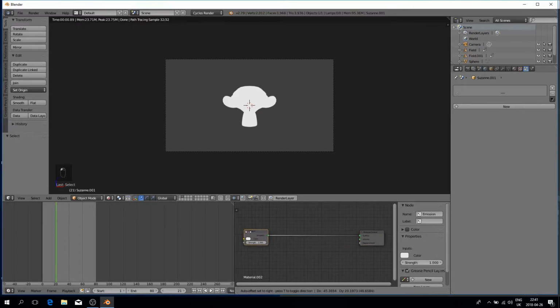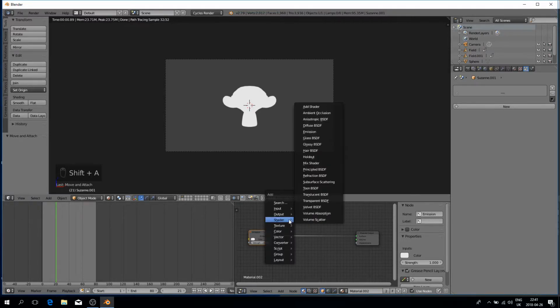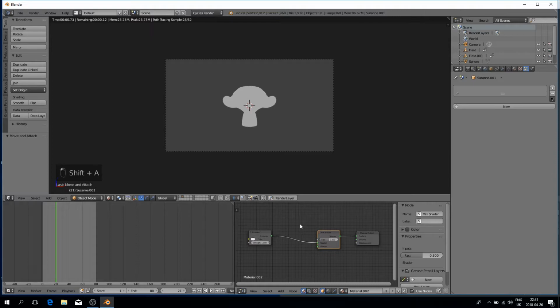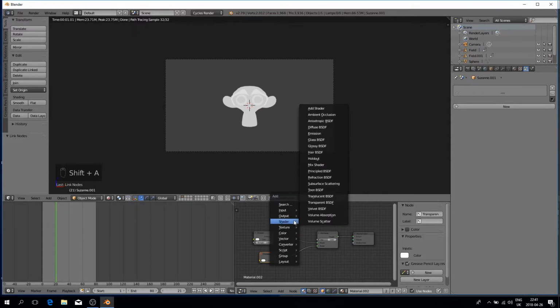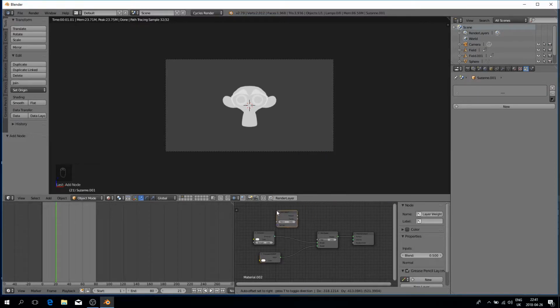So for that, we can fix it or make it look a bit better and get some details if we add a mix shader and a transparent shader. So it's getting there. One node that I found kind of looks good for sci-fi looking materials: if we go add an input and add a layer weight and add facing and click to the tab there, layer weight kind of gives the edges of the material, the second material here.